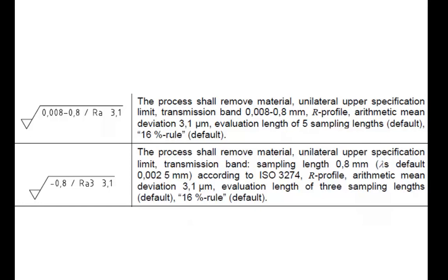If a total of not more than 2 measured values are greater than the limit, this means the surface is of good quality. Out of 12 measurements, a maximum of 2 measured values may be greater than the roughness value shown on the technical drawing.